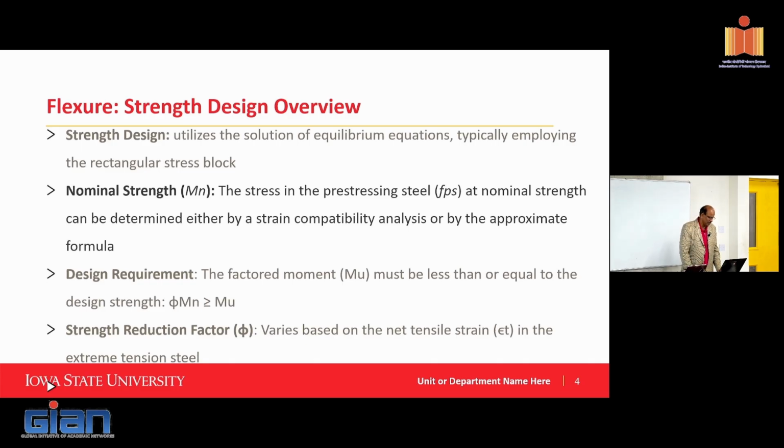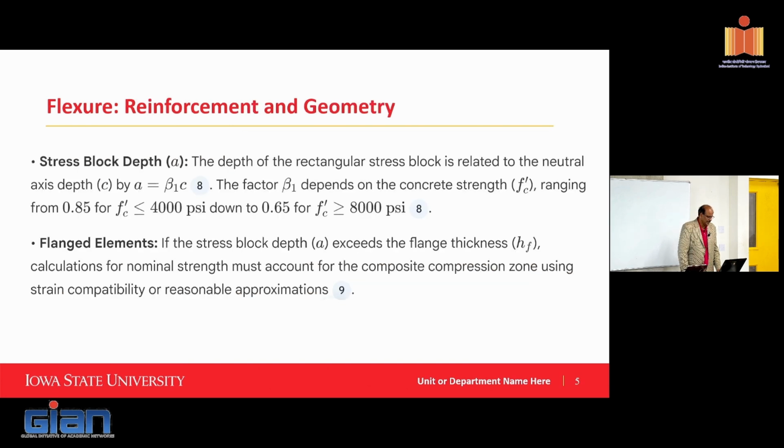In terms of completing the design, basically the factored moment has to be shown to be less than or equal to the design strength, and they provide the strength reduction factor based on net tensile strain. Is that what you also use right here?